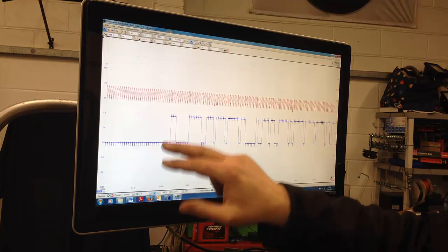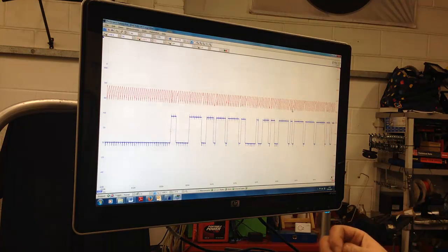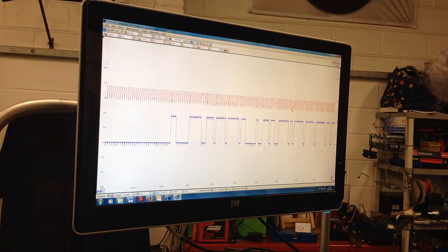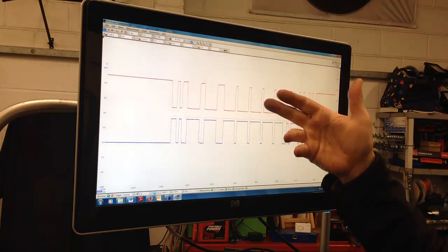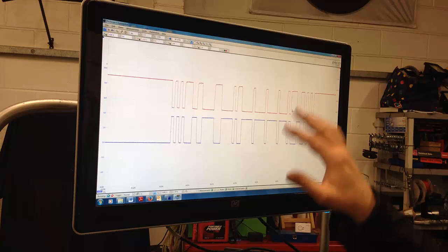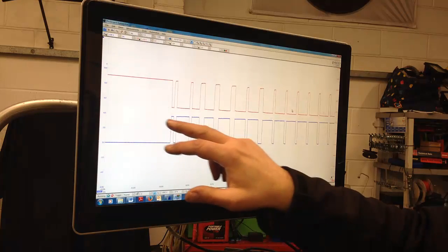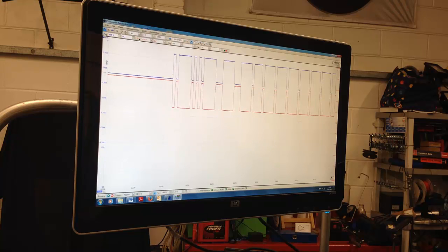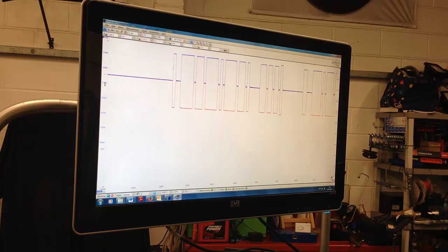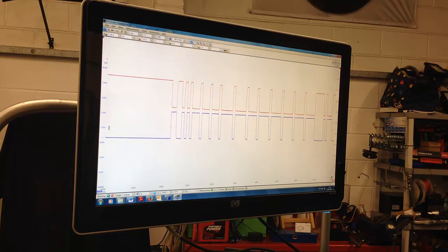So here we've got a CAN, 5-volt CAN signal here, and the other one which is disrupted at the top. Now we plug the new network in. What we're looking for is we should get a good reflective signal. Hit the space bar. This is now live from the car, and we can see straight away the two waveforms that we've got, good and bad CAN. We've got CAN going from 5 down to 1, and then we've got it going the opposite way, from 0 up to 4. So if we were being absolutely technically perfect, we could put one above the other to take a look at the way that the network signals are going, but we're happy just to see that the signals are reflected, one to the other.